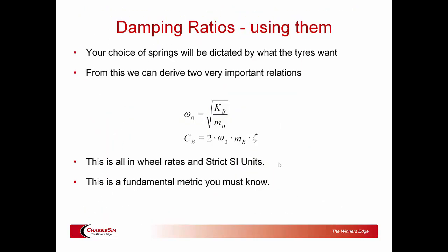Okie dokie. Right. Our next stage in the process is selecting our springs and geometries, because that will affect our tire heating. We can do that using the track replay simulation with Chassis, where we turn the internal temps on, or you do it via testing. It really doesn't matter. But once we have that, our next port of call is to use damping ratios.